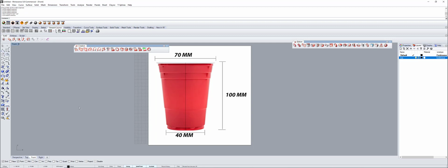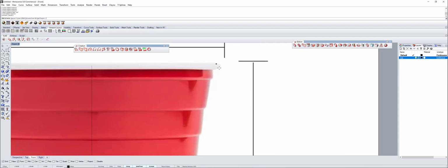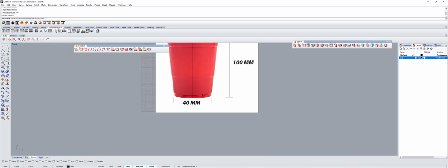So what I'm going to do now is go to this menu over here, control point curves. Sorry for my English again. There is a little arrow over here. I'm going to click it and it's going to open more options, and I'm going to use this one, the interpolate points. Click it, and now you have that little point over there. It's telling you that it's ready to draw something.